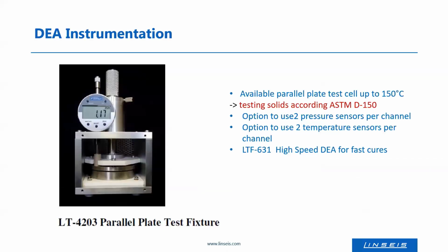There are a lot of accessories available, like parallel plate test cells. The sample is placed between the plates and also the sensor, and then you can apply pressure. You can measure that pressure. You can heat up with that test fixture, and there is an ASTM norm for testing solids with that parallel plate test fixture.